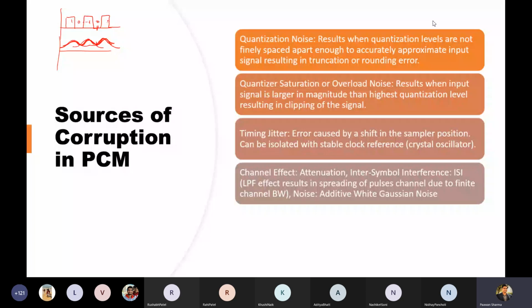Sorry. Then you have noise impact. Noise, whenever it comes, we represent it as AWGN. Has anyone seen this term earlier also, AWGN? Yes. Please, can you tell something about it? It's additive white Gaussian noise. Okay. And it is basically a number of frequencies which have the same amplitude throughout the transmission. Good. So white means it is expected to cover a wide range of frequency, a very, very large bandwidth.